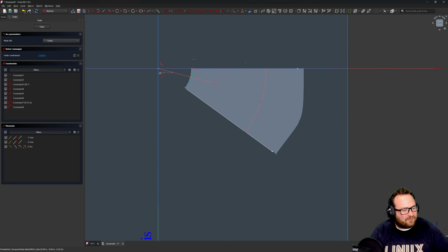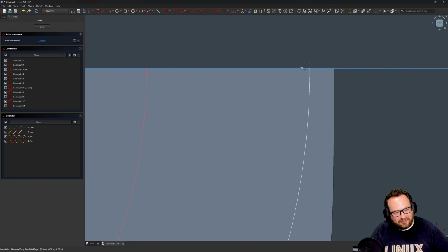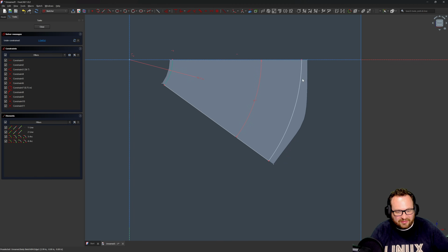So we're running right on the edge of that surface. We'll make one final arc. Again, starting from the origin, we'll go to the other end of the line and the other end of this line, just like that. Now, I don't think those merged, so I'll grab coincident with the C key and add that. Now, what radius do we want that line? I think that's our last degree of freedom.